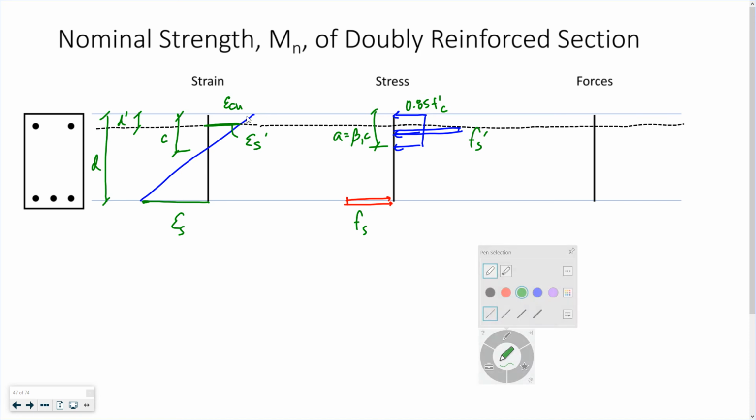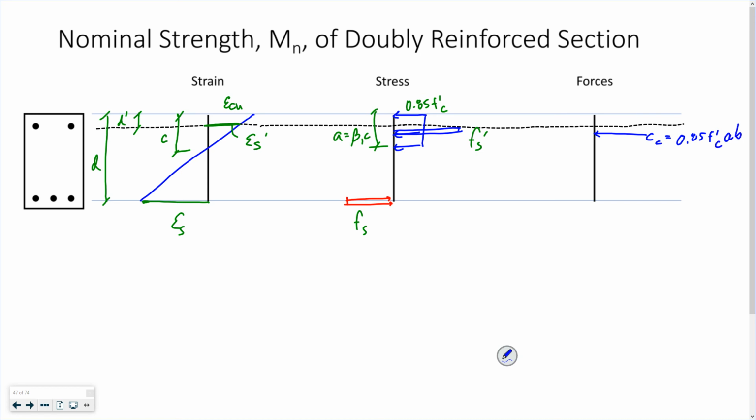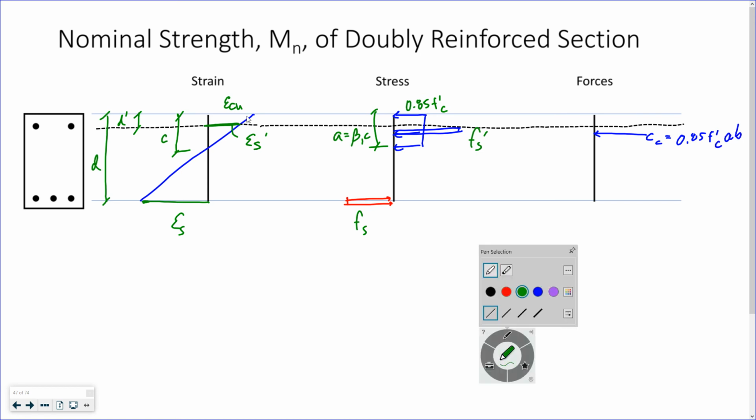Going to resolve those stresses into my compression force in my concrete, which is equal to 0.85 f'c a b, right?